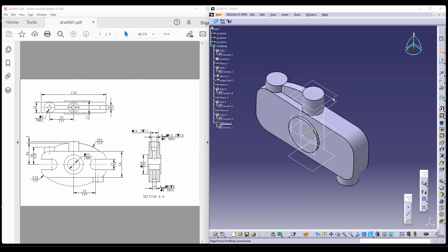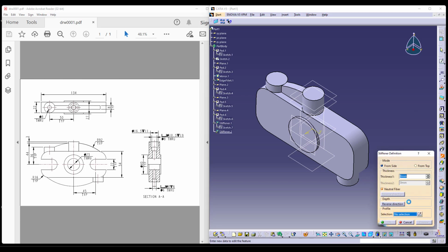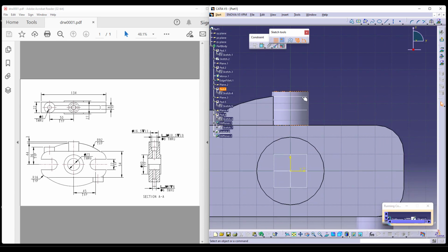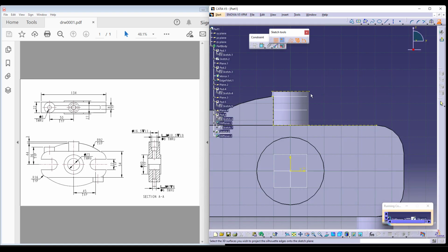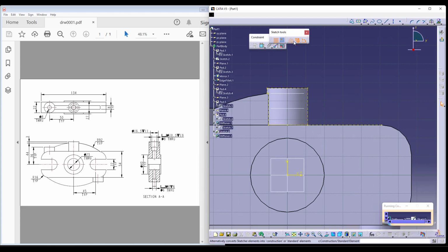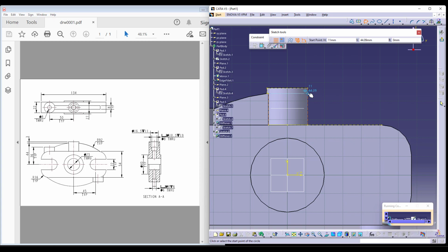Now let's try to make the other side as well using the same stiffener and selecting the center plane. First, let us try to take our references and then proceed. And then the silhouette reference as well. Now, the arc actually is starting from here, which is inline, and then goes till here, as you can see.